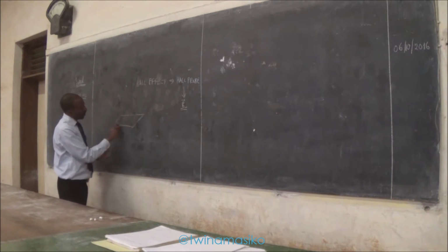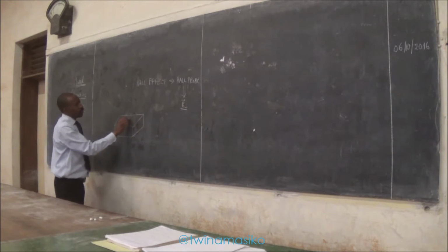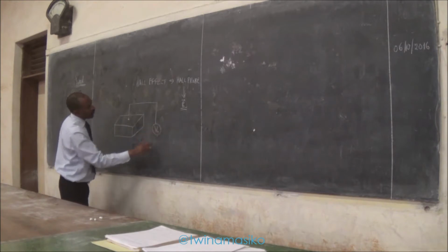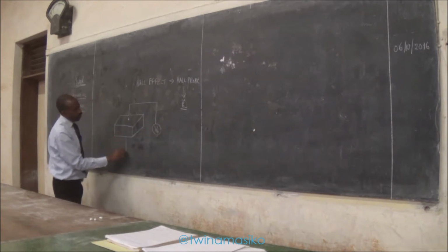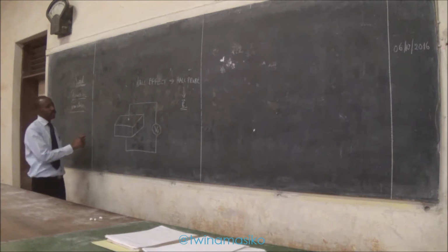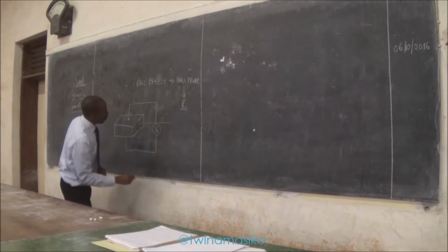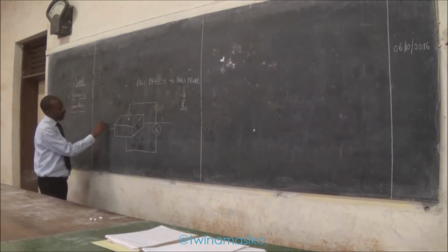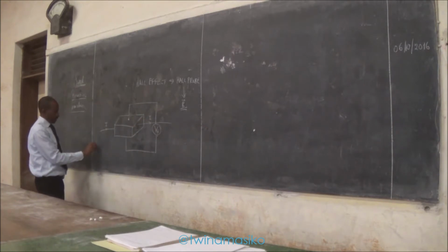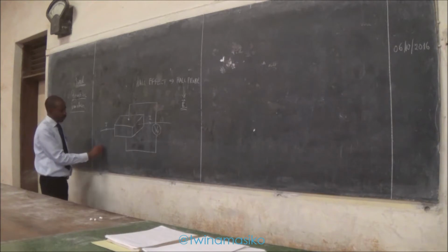After chopping a semiconductor wafer, you had to put on its sides a high resistance voltmeter, which you were going to use to measure the Hall voltage. And then you had to pass the current through this conductor. So I here was the conventional current. I'm just denoting the point, so you don't need to write. This was the conventional current.